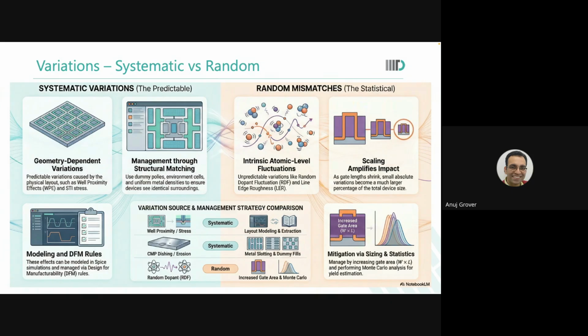So something will happen. The density of STI could be a little different, so STI also has silicon in it. It is silicon dioxide. So it could have a different density than silicon itself. All those physical parameters, the fact that there are dangling bonds, or the bonds that are now, instead of silicon connected to silicon, there is some interaction happening between silicon and an oxygen atom at that interface. So all those things result in a differing behavior in the channel also.